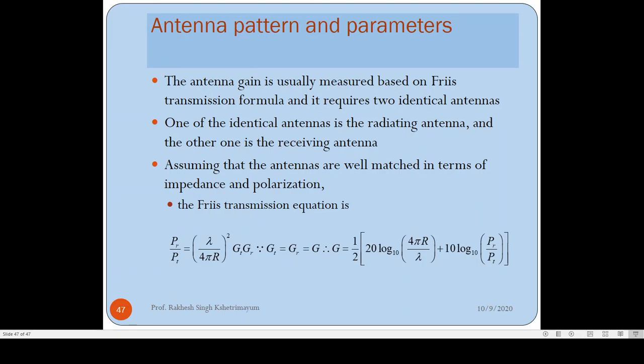And we have seen that an antenna can have an omnidirectional pattern, it can also have directional patterns. And we have also defined what are the main lobes, side lobes, how much is the side lobe level. Lower side lobe level is better for us. Lower front to back ratio of the antenna is better for us. We have also defined theta max, direction of maximum radiation. And we have also defined half power beam width. A broader main beam will have a larger value of half power beam width. We have also defined beam width between first two nulls.